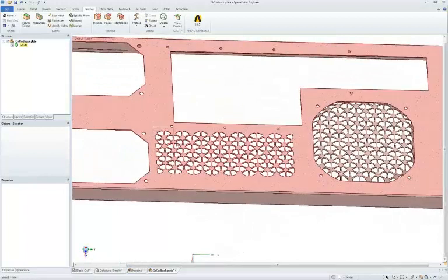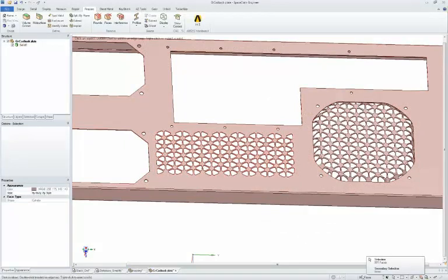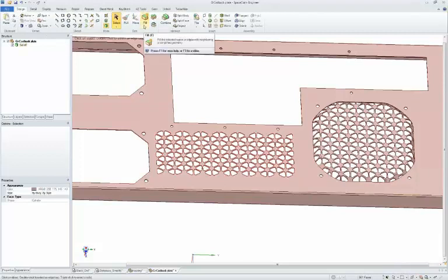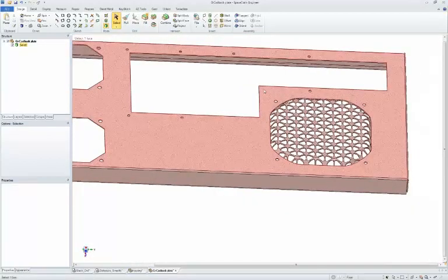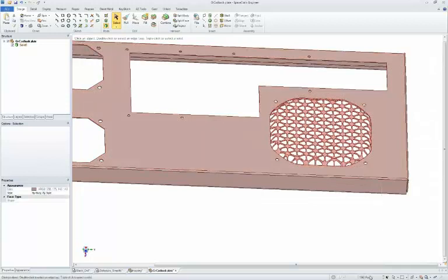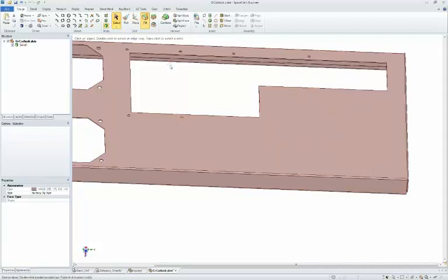So again, a nice box select will grab the geometry that's there, and that's 900 faces. 900 small, tiny faces that by filling in, I can get rid of. Or even all of these faces here. If I want to grab them and eliminate them, that's 1,300 faces. Fill gets rid of them, removes them from the model.